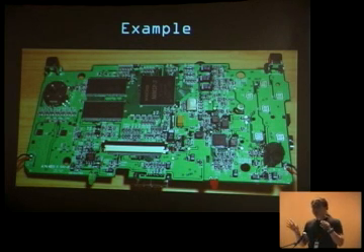And you can start strapping, the thing will freeze and reset and start talking to your JTAG protocol, right? So you can sort of do that with high impedance resistors and eventually discover the port, if you don't have the manufacturer data sheet. So, back there. How do you recommend we go about that?